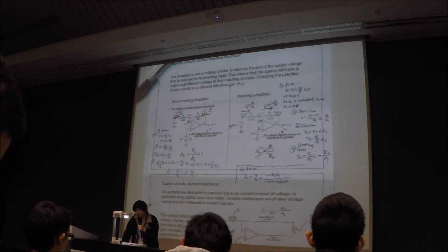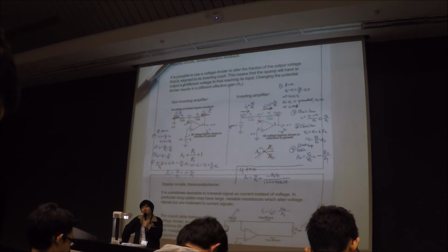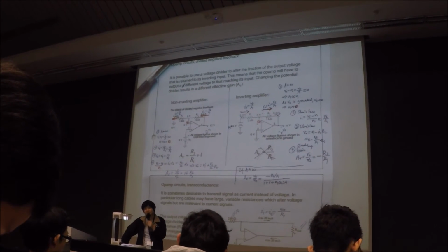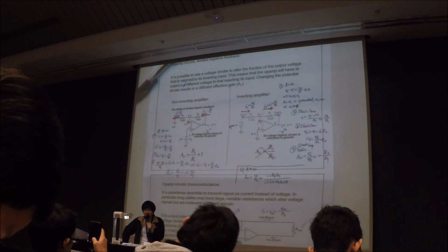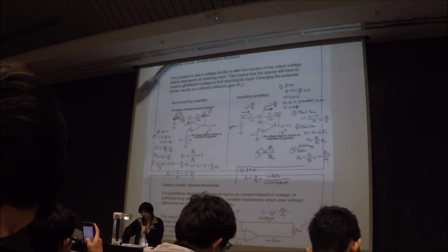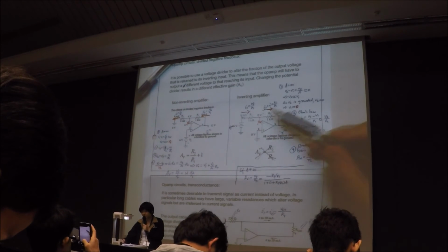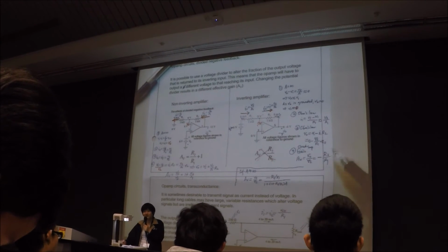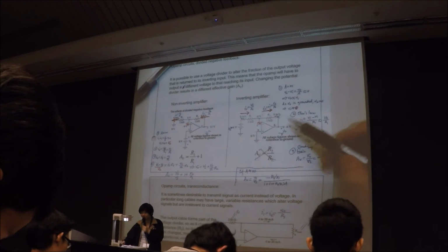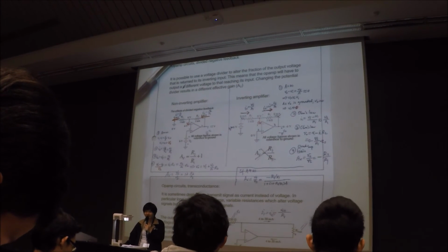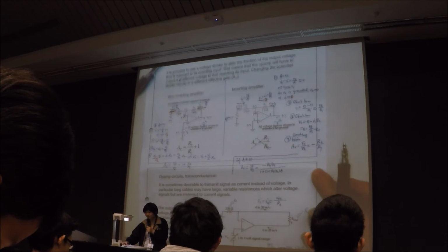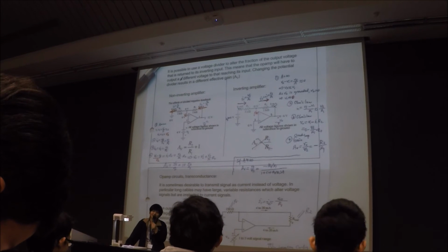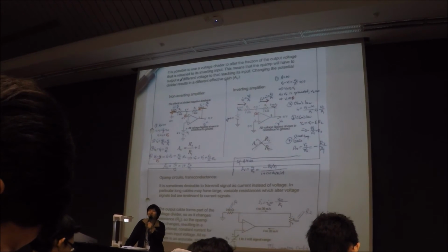As you can see, for the open loop configuration of the op amp, its amplification gain is approximately infinitely big. But due to connecting the output to the negative terminal, the amplification gain becomes a finite number, determined by the two resistors that you connected. Of course, this is all based on the assumption that the open loop gain A is infinite.